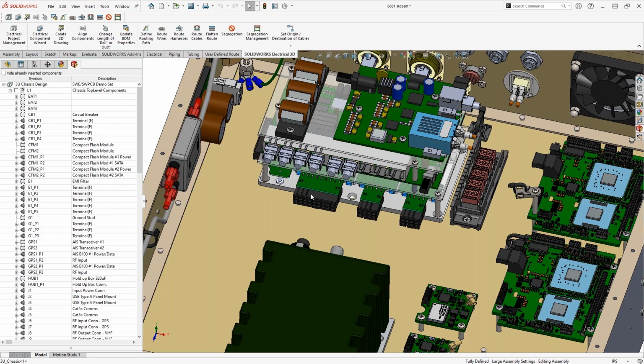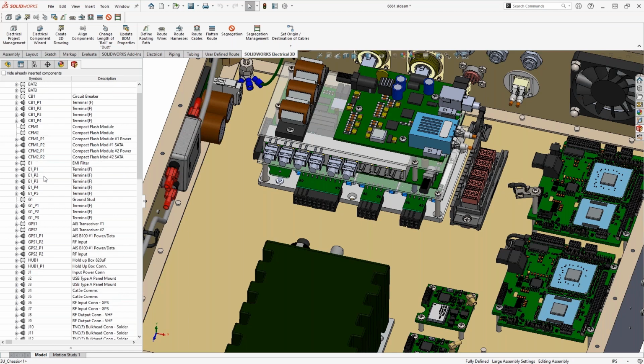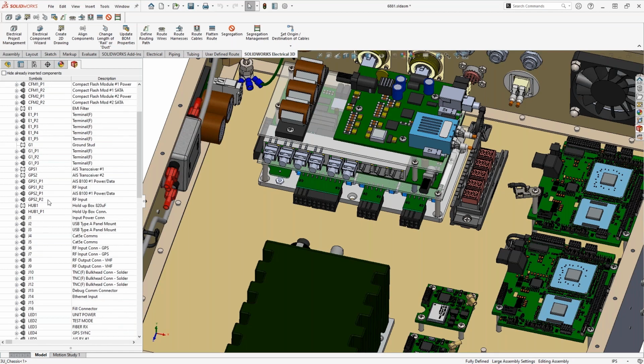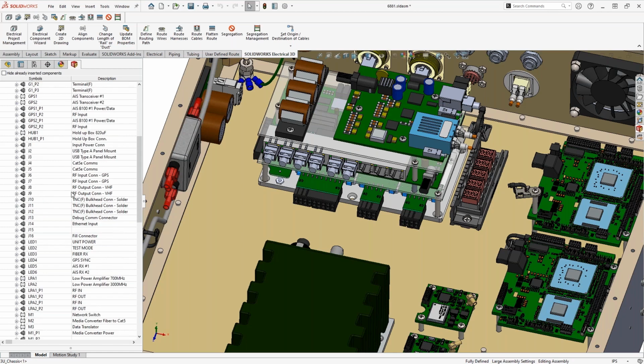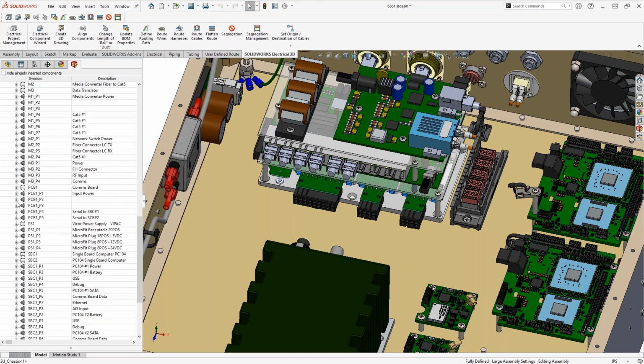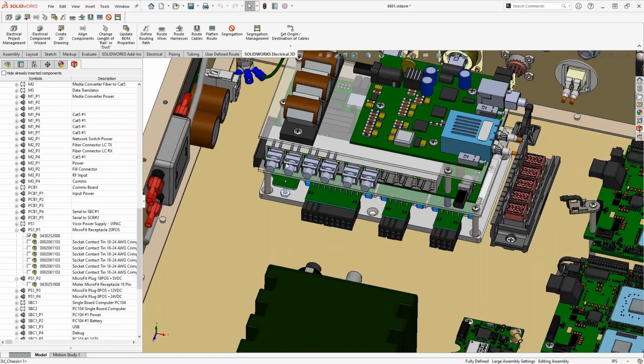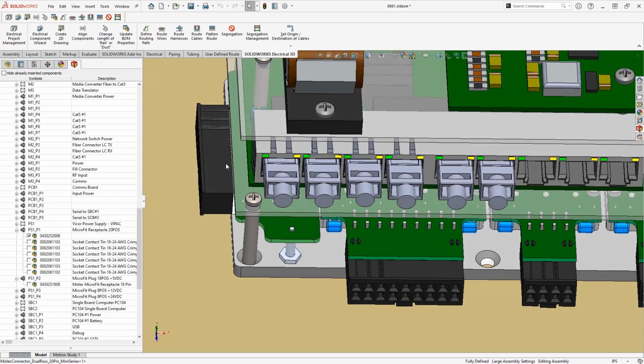The mechanical engineer might come in and say, all right, give me the models, and I'll mate everything up for you just to make your life a little easier. Well, there's 2 options with adding or inserting your parts to your assembly, right? Like I just said, the mechanical engineer can take all those and start slapping everything in and mating everything up, but might not know what is what, right? There might be 15 of the same exact connector. So in this case here, I'm going to go ahead and find my power supply, and we notice that I have PS1, which is this one down here in the back, right?